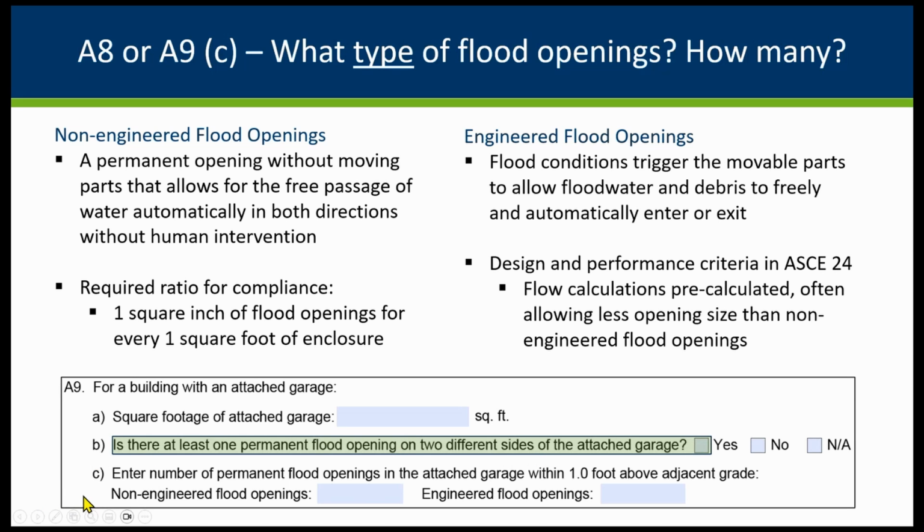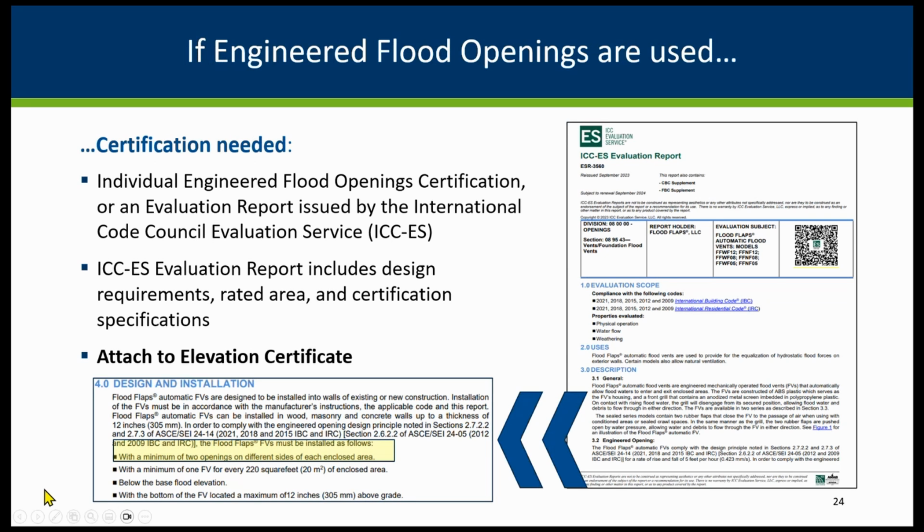Now, if you are using engineered flood openings, just a reminder that the certification must be attached to the elevation certificate. If the certification that comes with those engineered flood openings is not attached to the elevation certificate, you must treat those as though they were non-engineered flood openings. So that's pretty key if you've got those engineered flood openings.